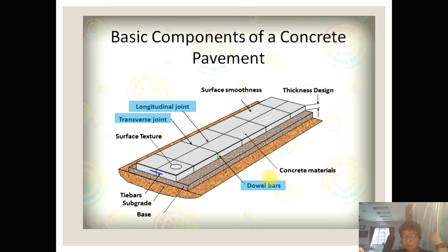As we all know, concrete will expand during the day because of high temperature, and during the cooler night, it will shrink. If you cast this slab as one piece, there will be a problem. It cannot keep expanding and shrinking repeatedly, or the concrete will start to crack.